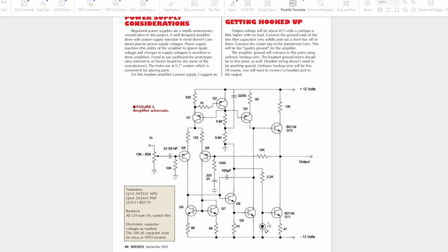So the forward voltage of this LED is quite important to get the correct amount of current flowing in the output stage. But the difference between 2.1 and 2.3, there's not much in it. So I'll try that particular LED and see if it works. I mean, if anything, either the circuit will work or it won't. And then I'll just try a different LED. So what I'm going to do is breadboard this circuit up, and I'm going to run some tests. So I'll spend the next hour or so fleshing this out on breadboard, and then we'll come back once the circuit is assembled and start testing.